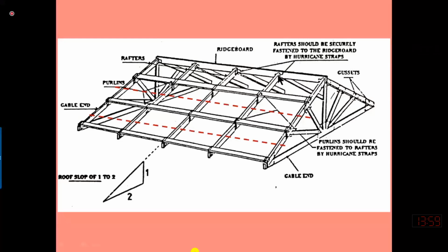They do not let the purlin move in the lateral direction. If we break up the purlin into different segments by providing sag rods which constrain the lateral movement, the design will be economical. How many sag rods we need to provide, we can decide based upon these guidelines.